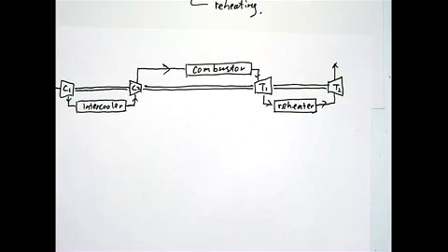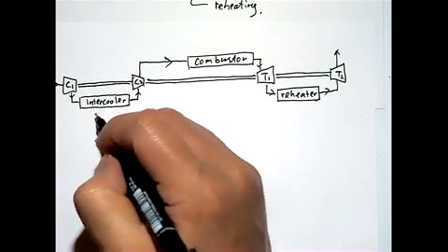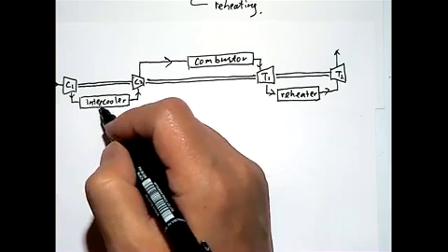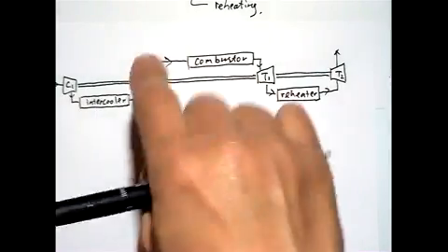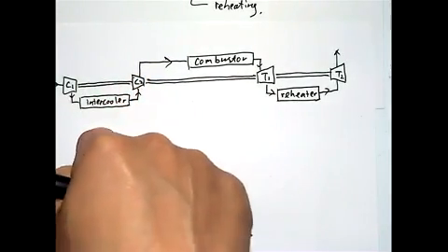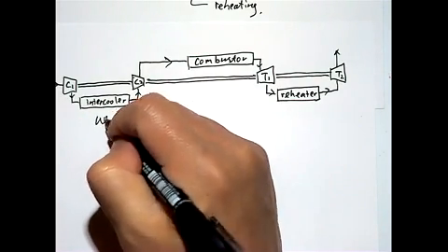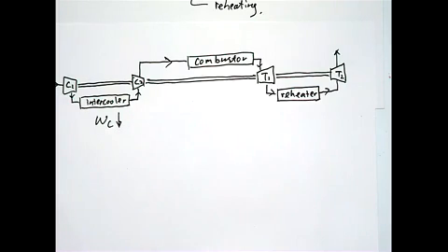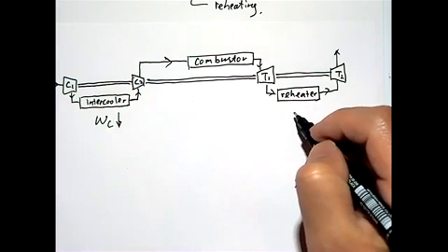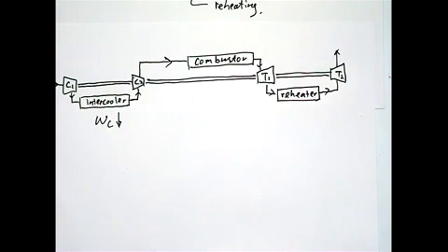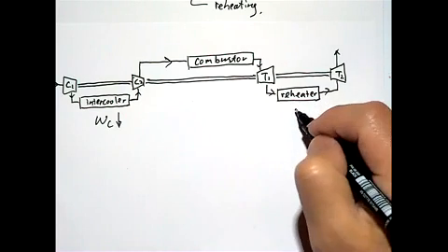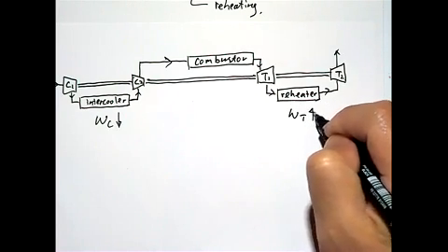Right. So the idea, again, as said, with the intercooler, you take away some of the heat from the system and keep the volume low to reduce the compressor work. And in this case, you keep the volume up to increase the turbine work.